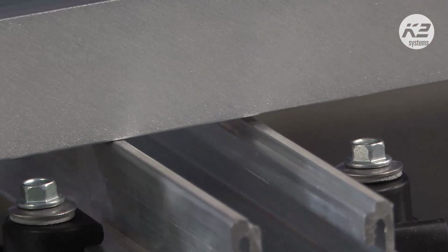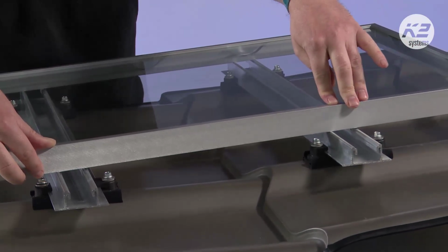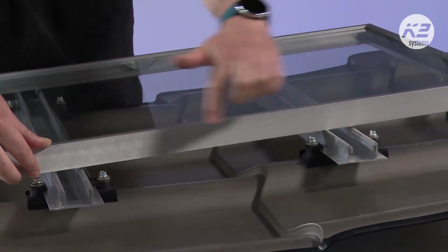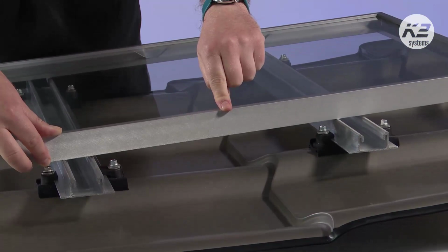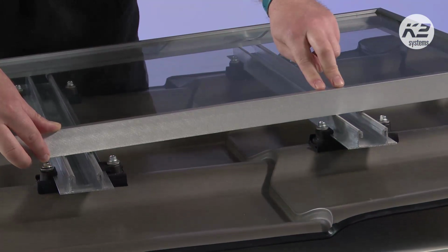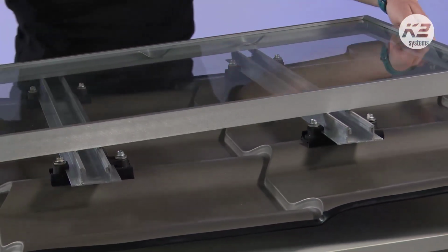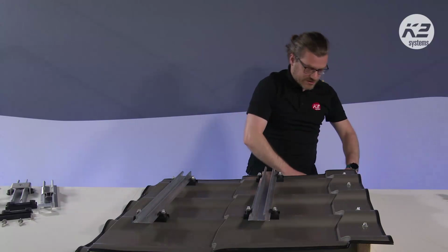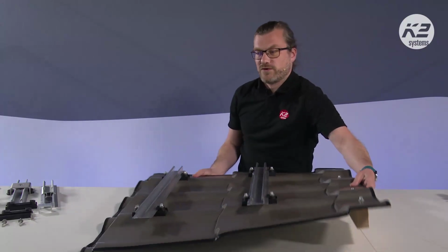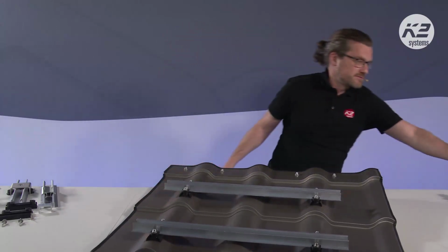Even for this short distance between the basic rails, you already see this gap. If you try to push the module down with the clamp, you will create tension here. The bigger the distance between the rails, the bigger the tension, and this can lead in the end to cracks in your module surface, and you will damage the module. This is the reason we wanted to develop a special solution for this type of roof covering. So we came to our FlexAdapter. What is the FlexAdapter?